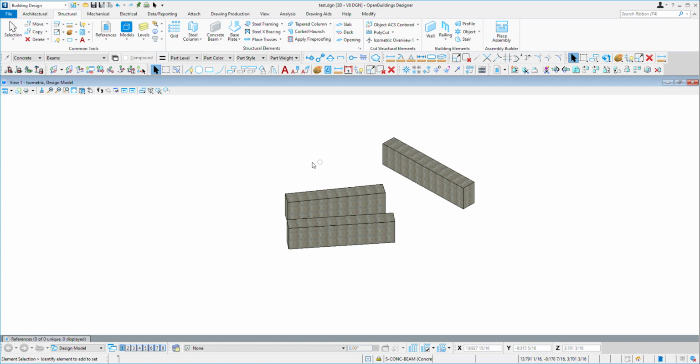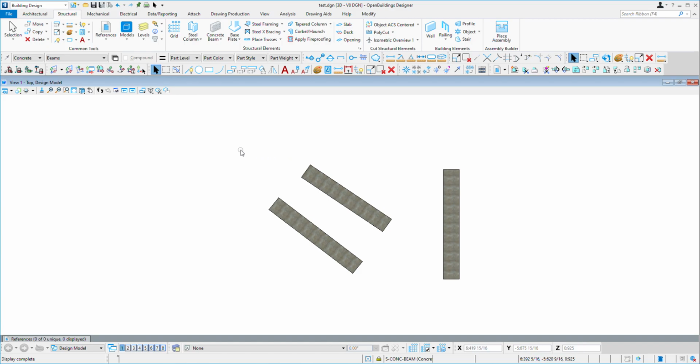And next thing here, one of the features is also here. If you press shift and control and right click, all the things come up here. If you want to change your view style, you want to see top plan, bottom plan, whatever you want to see, and you want to see the 3D model, you can arrange it easily here.